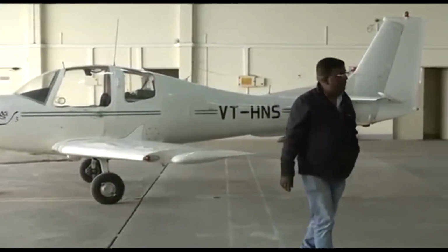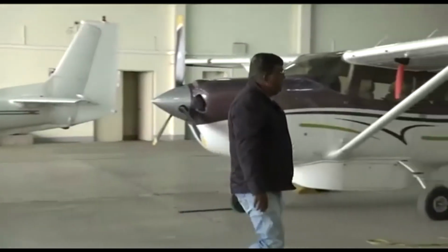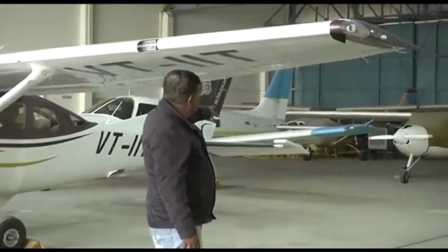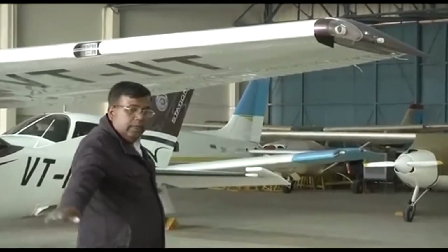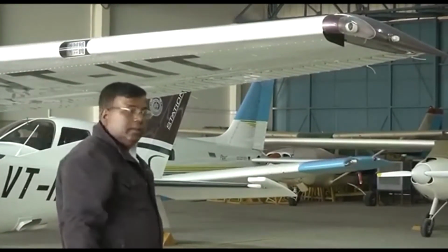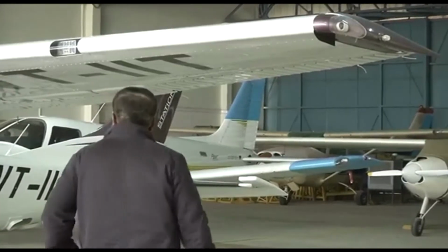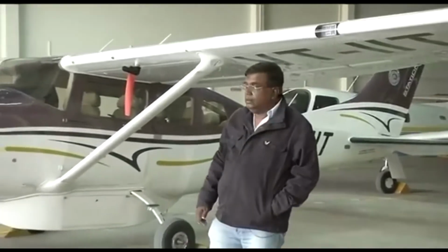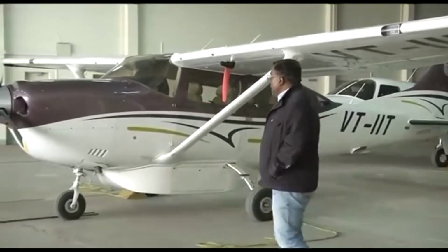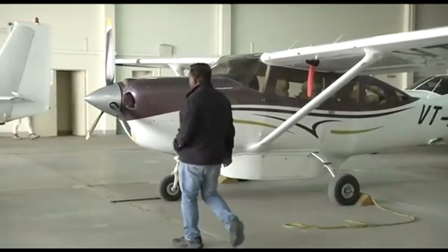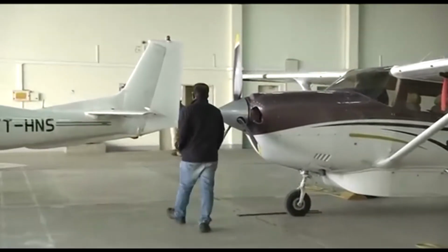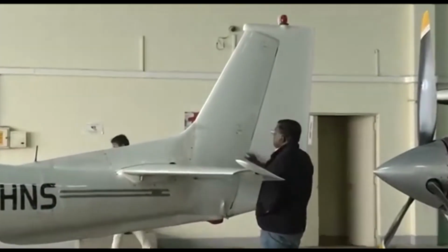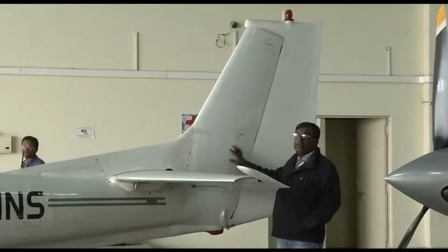And if I see another airplane, which is at the back of Cessna 206, that is also a low wing, but having appreciable dihedral. That is, a low wing with some dihedral given. Okay. These are important aspects for giving lateral stability to the airplane, right? Also, you should understand that the vertical tail, the whole of this, is extremely important for giving lateral stability.